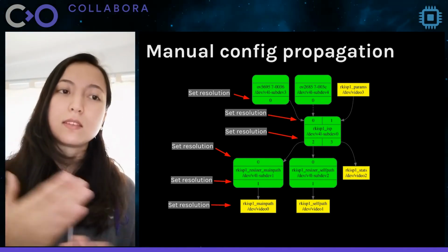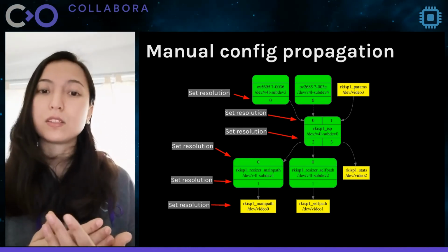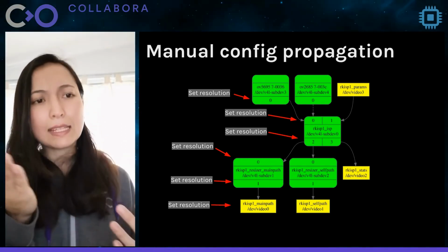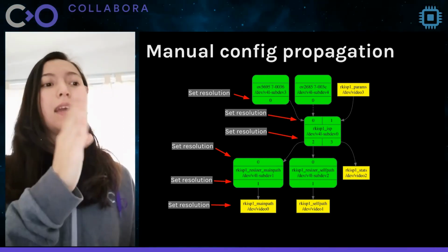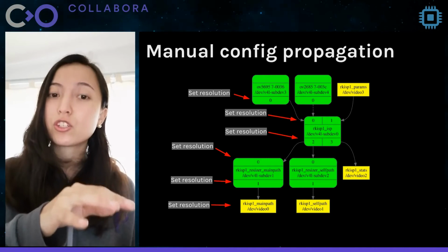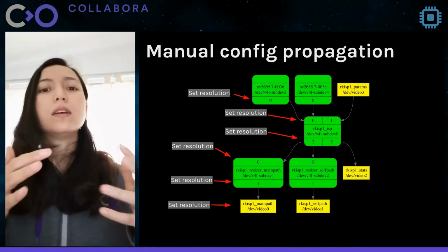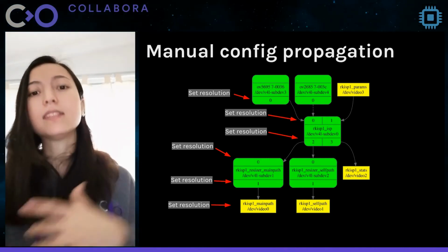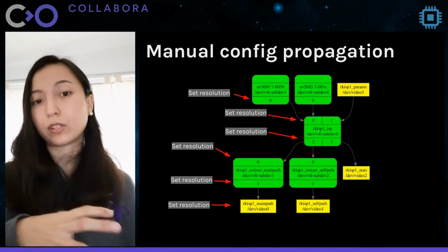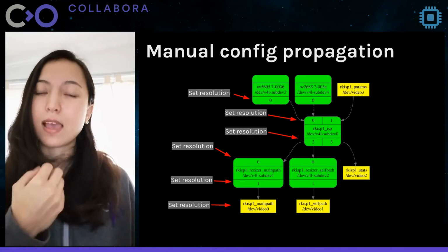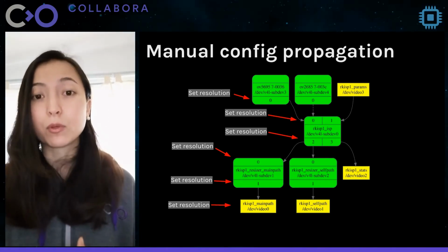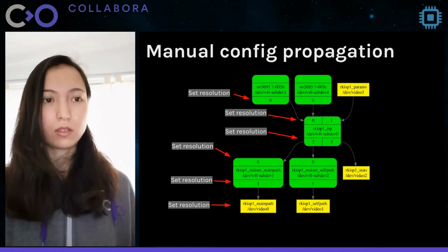Then user space needs to configure the resolution that the ISP needs to generate, and it needs to match the resolution that the resizer expects, and needs to configure the resolution that the resizer should generate, so could be bigger or smaller to zoom or shrink the image, and finally setting the resolution that is expected inside the memory buffer for the final image.